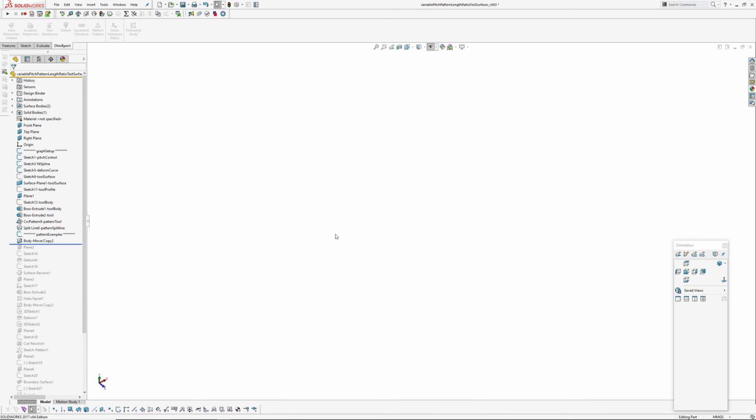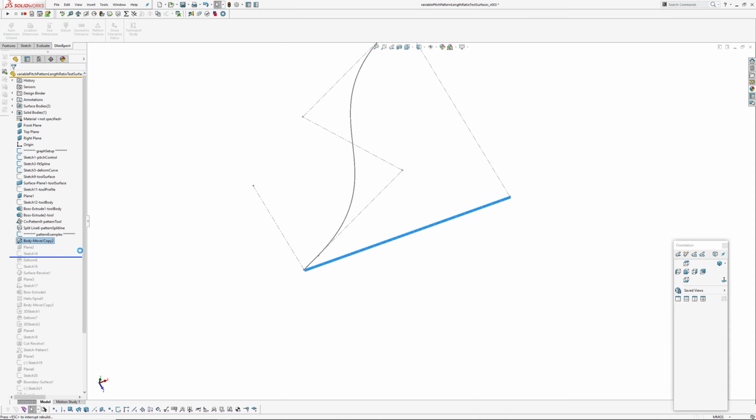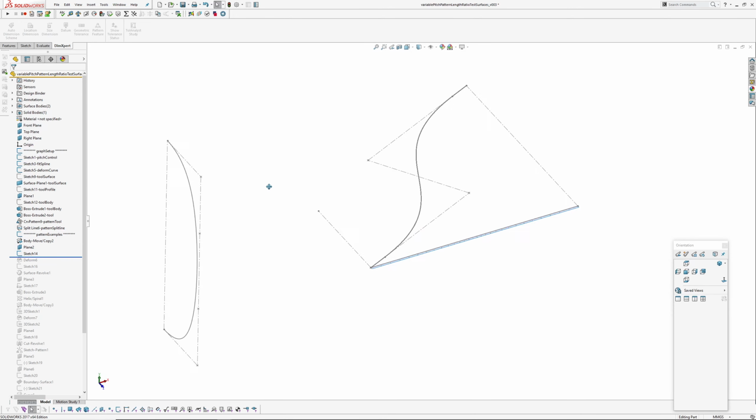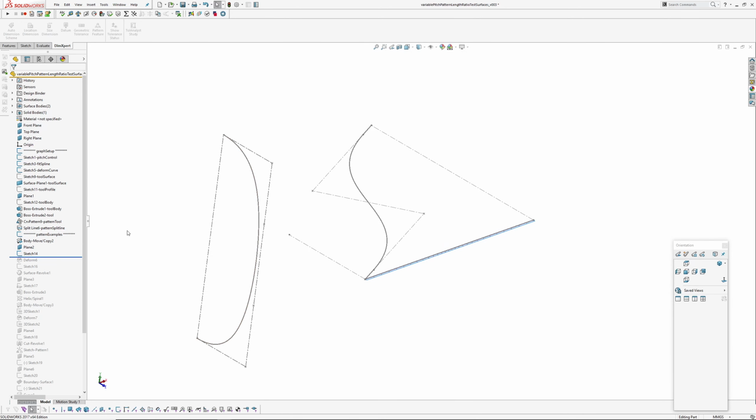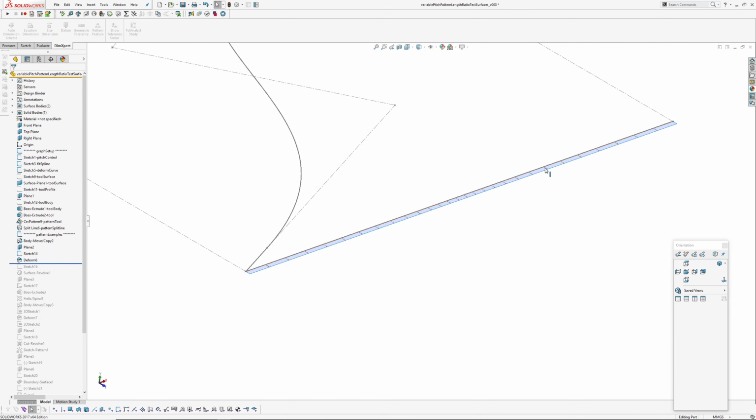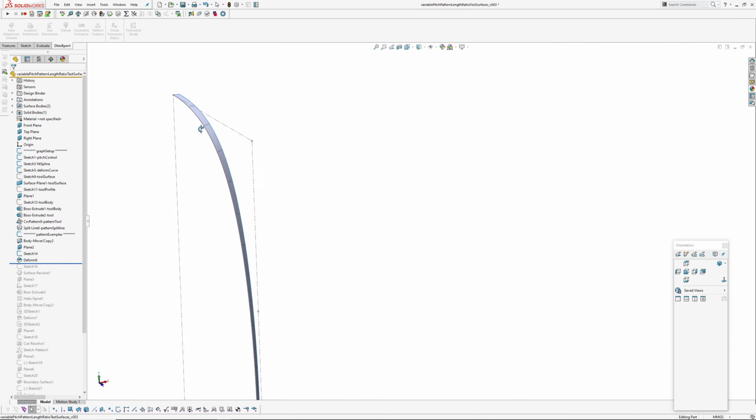Just roll back here, and I'll go through how you apply the pattern tool to a spline or any curve. I've just made a couple of copies using move body copy without a transform. Here I've created a spline, and then I've used Deform to remap the tool ribbon along that spline.